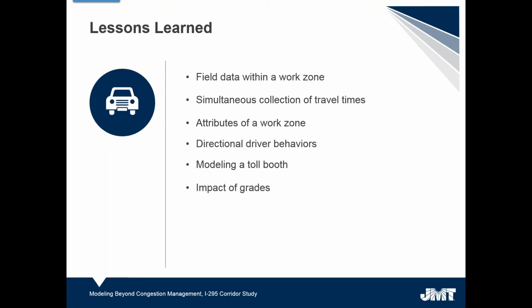But one of the reasons is that when you're on the Delaware side, when you're coming from the south driving north, there's much more interchanges and lane drops and more interactions and more characteristics of the roadway that would have a driver drive differently there. Another lesson we learned was how to model a toll booth, and also the impacts of grades that they had on the models.